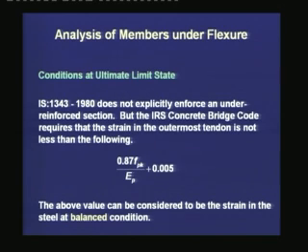That means, since we do not have a definite balanced condition, if we want to define a certain balanced condition, then we need to define a particular value of the strain which the steel should have when the concrete is reaching its final strain. Now, depending on the code, we can define a balanced condition, and here we see a value which is recommended by the Indian Railway Standard Code for the concrete bridge design.